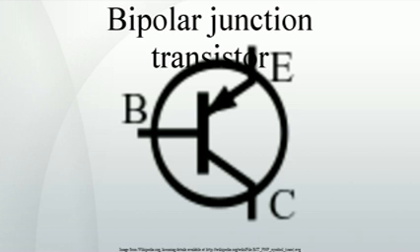Transistor parameters, alpha (α) and beta (β). The proportion of electrons able to cross the base and reach the collector is a measure of the BJT efficiency. The heavy doping of the emitter region and light doping of the base region causes many more electrons to be injected from the emitter into the base than holes to be injected from the base into the emitter.